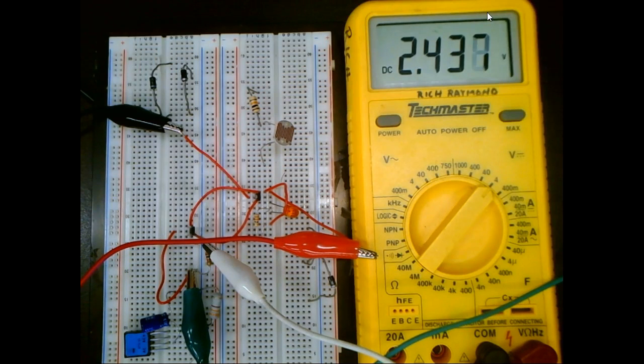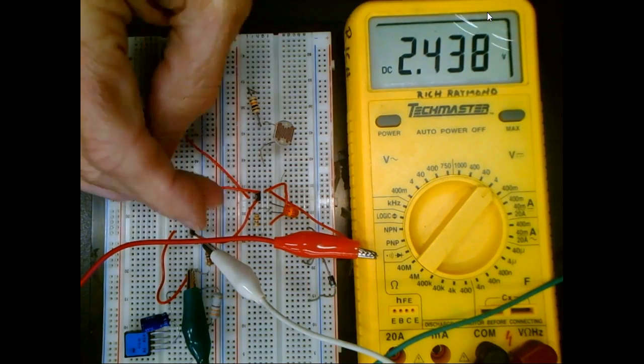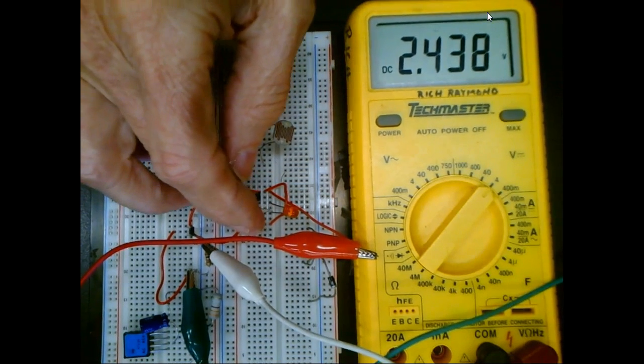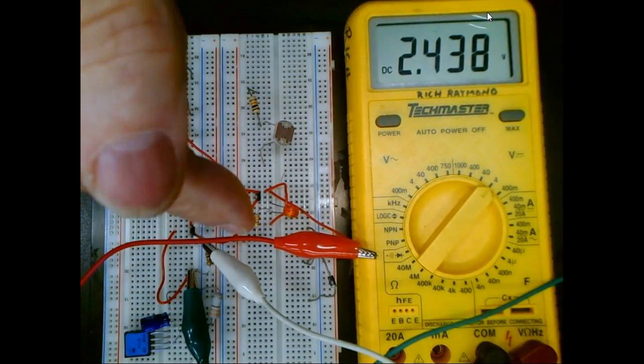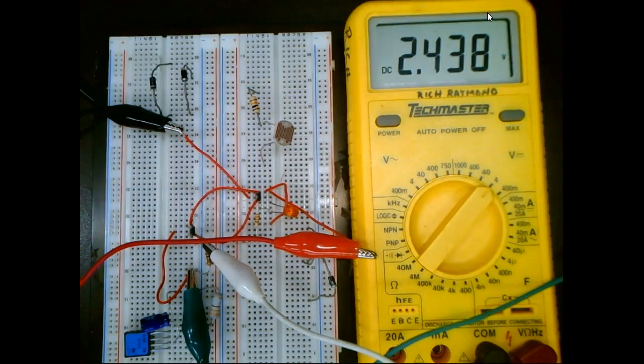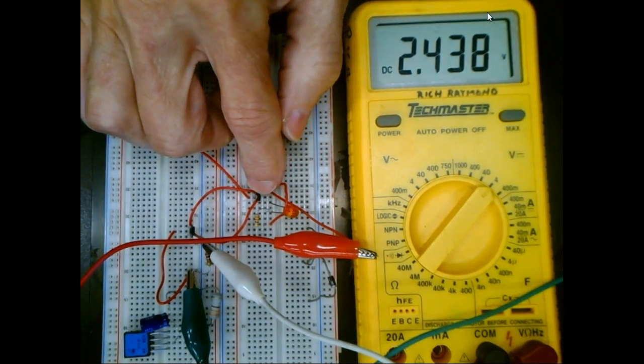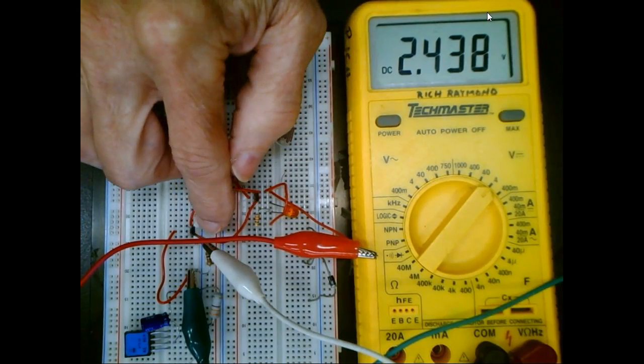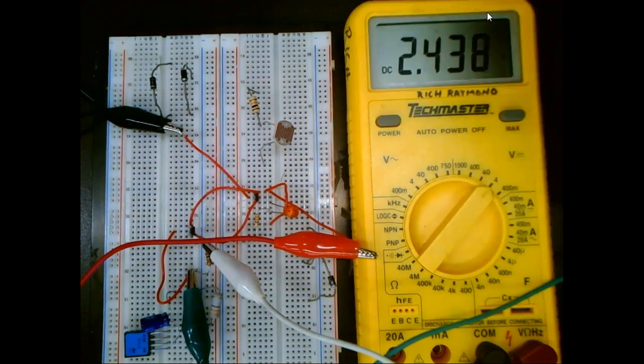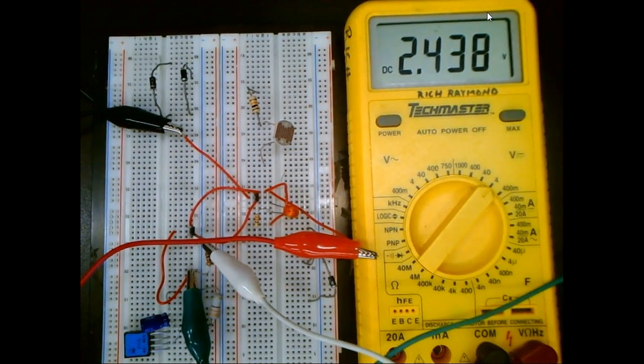Now, this guy here is a source. It's a sourcing sensor. So I had to put my resistor in between it and common, right? You understand? Between it and negative, not common negative. So this is linear. This is the latching. This is linear. Now, the only difference is the electronics inside the sensor when they make it.